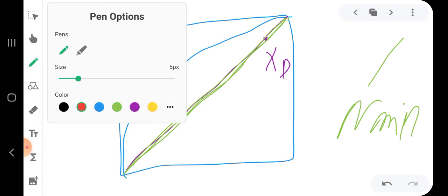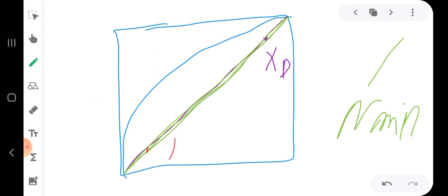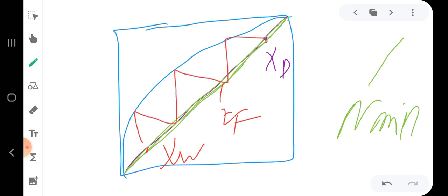If you draw the stages starting from xd to xw, for example, with your zf point here, assuming that the operating line coincides with the 45-degree line, you're going to get the minimum number of stages.